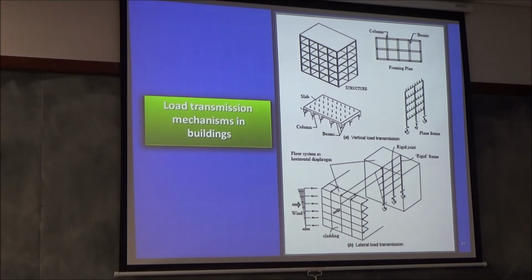Let's consider a rigid diaphragm. If all the frames move exactly the same, what does it tell you? It tells you, because lateral stiffness is what decides how much it will move, that all the frames will take the same load. So this assumption of tributary area, that due to wind load only the middle region will take 2 times, is a stupid assumption. Stupid? You don't like the word? Many colleagues are stupid because they make this assumption.